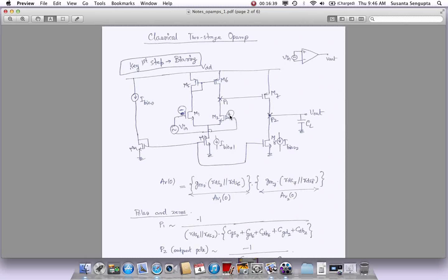That's why this is positive. A positive here makes a negative here. That makes a positive here, so it makes sense. This will be the positive terminal. If you increase this node, the voltage here increases, it will increase Vout. Okay, so that is the terminology that you will be asked about in many circuits: to check which should be the positive or the negative node.